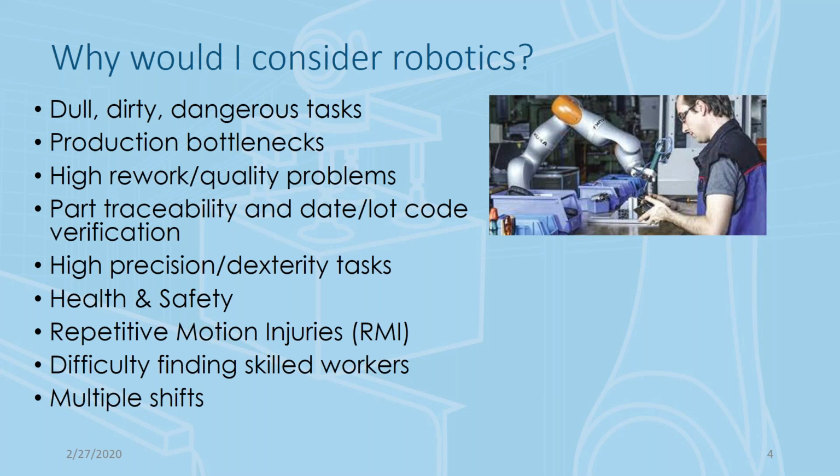So what we typically consider initially for robotics applications are those high volume processes. So when you're making hundreds of thousands of parts per year and you're having high speed, high volume, that's where robots really excel. Another way, the corollary of that is what I call long duration tasks. So that could be, say you're welding parts on an I-beam, for example, and it may be 3 or 4 hours to complete the weld of that entire part, or a fuselage on an aircraft.